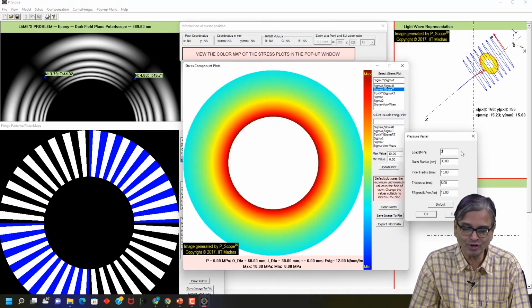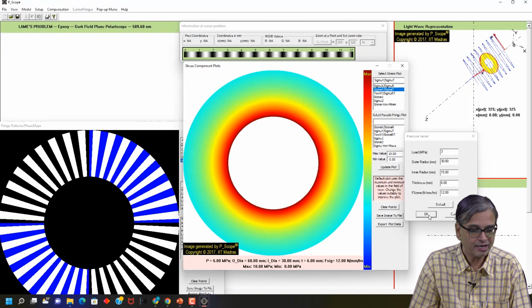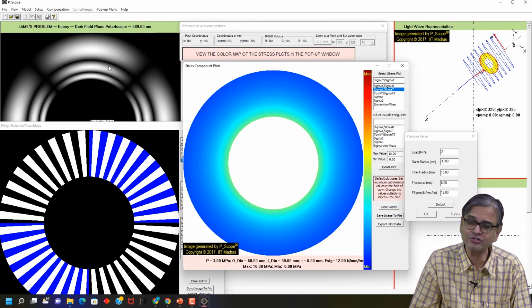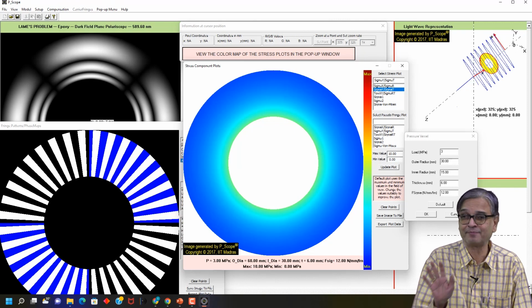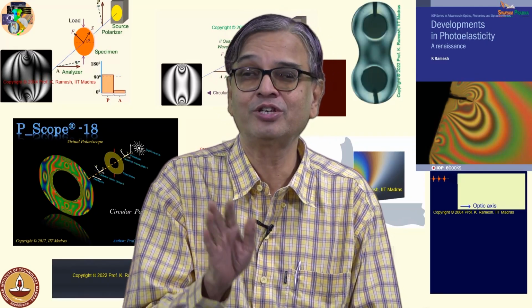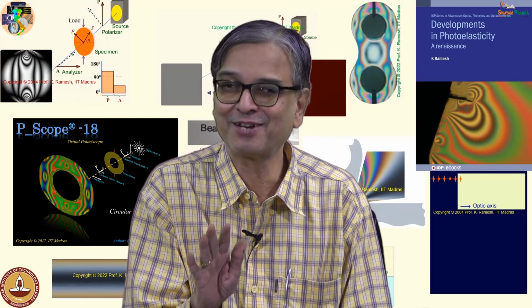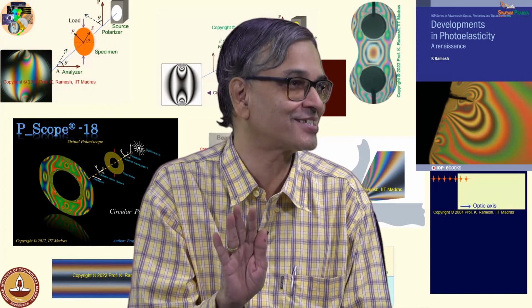Now, I have reduced the load by half. Let us repeat the whole thing. I have the fringes reduced, and then I have the stresses reduced. The isoclinic remains same. The all isoclinic also remains same. See, don't tell me that you are showing me a simulation. I don't know whether you calculated it or not. Take it from me that it is calculating it afresh for any one of the loads.